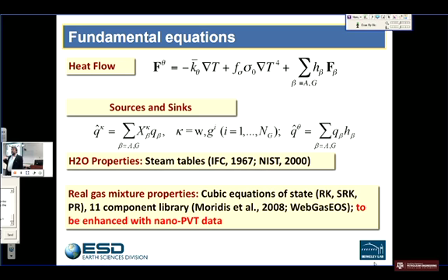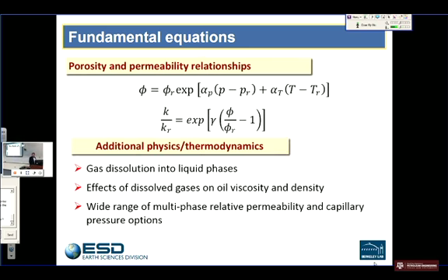So for this case, when we have this happening, we switch from the continuous cubic equation to tables or specific data. For example, we have the properties of CO2 there. CO2 is one of the worst materials to work with in terms of properties. If there was any justice, CO2 would have been a liquid, but it isn't. So you have different enthalpy tables for that, and that's what we do for the other gases. So this is fully accounted for right now. But when this comes into play, things may change significantly. We don't have that yet. Actually, nobody has that yet.